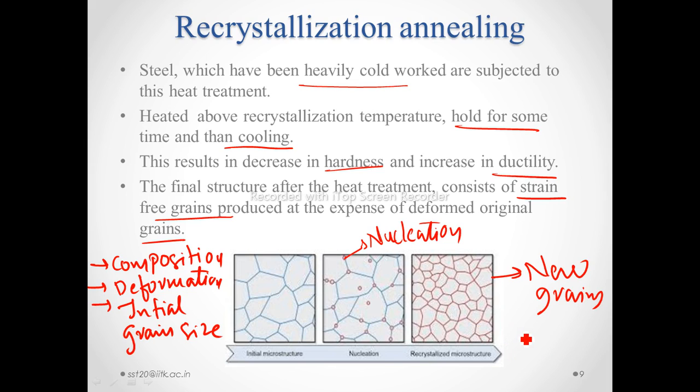In a composite material we add particles or precipitation particles to enhance its mechanical properties, but here just by the heat treatment process itself we are enhancing the mechanical properties. In many interviews they will ask how you can enhance the properties of a material without adding any component, any external alloying element. The answer is heat treatment. The recrystallization heat treatment process is a good example of this.